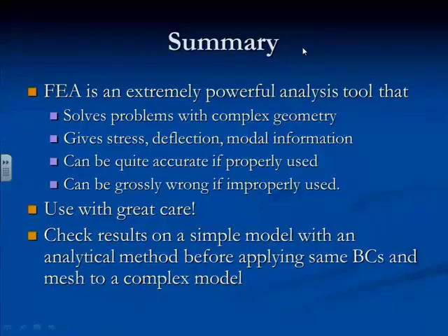And they can go in that and run Nastran on the body shell and find out what the modes of the body shell are. And then they can determine whether or not they have excitation frequencies in the engine at whatever speed that are going to cause that whole body shell to buzz like a drum, right? And they're trying to get out the NVH, the noise, vibration, and harshness, and they've done a marvelous job. I mean, the cars now are so much better in that regard than they were even 20 years ago. And it's largely because of this ability to do this very complicated modeling with the combination of CAD and finite elements to not just find the modes, but the stresses and the deflections.